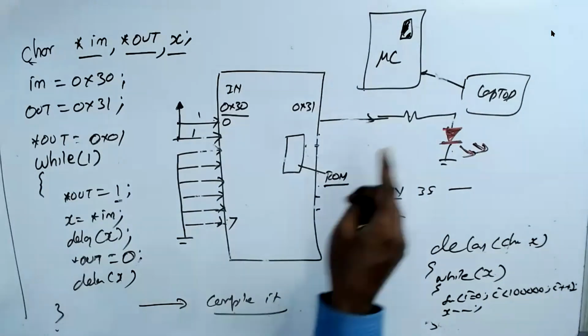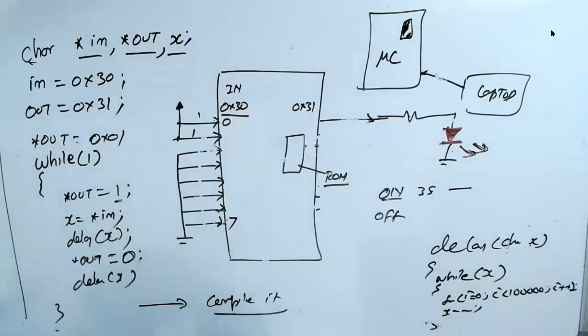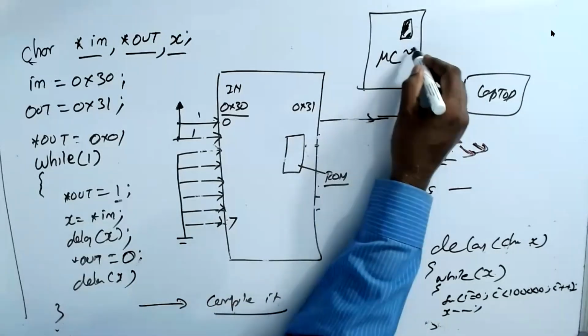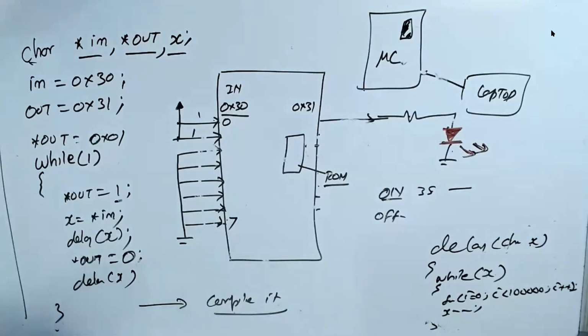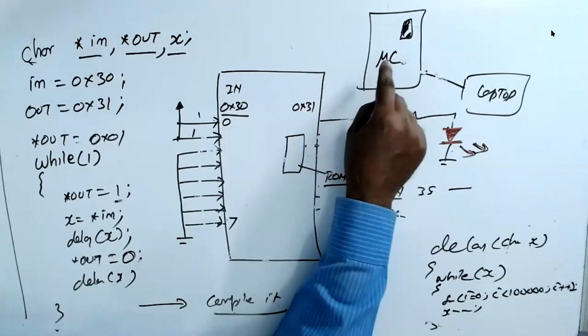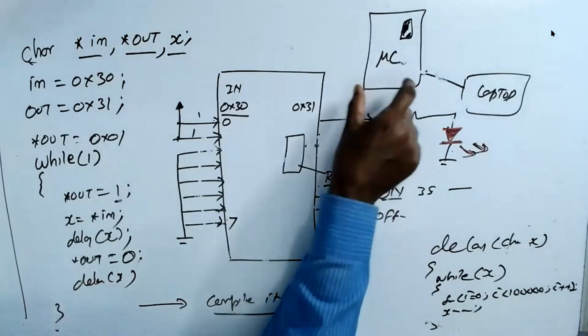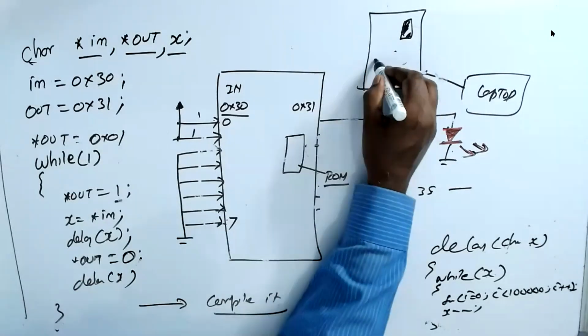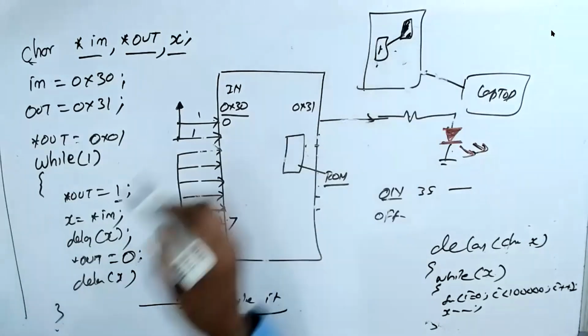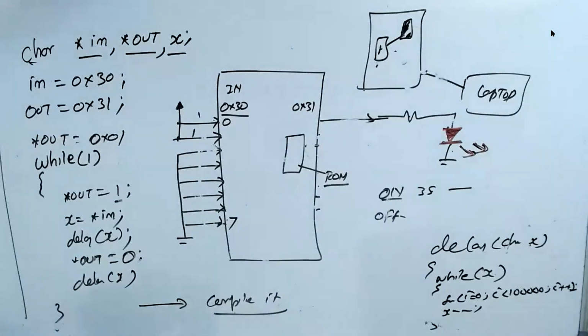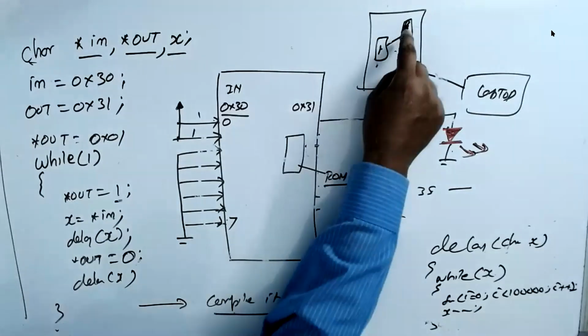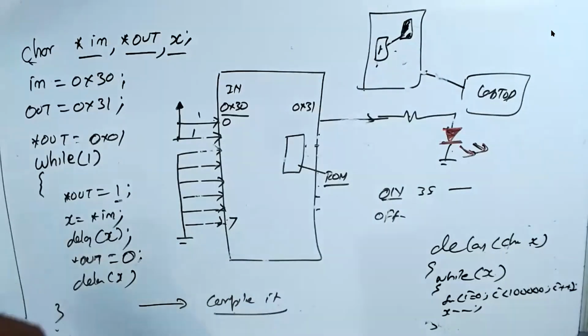But you can also make the ROM secure. There's a fuse inside. If you make it secure, then what happened? Nobody can read what is inside the ROM. Now the microcontroller will work because the microprocessor inside the microcontroller will read the code and execute. Let's say I write the program and give it to you. You can use the microcontroller, but you cannot change the ROM, or read what is inside.